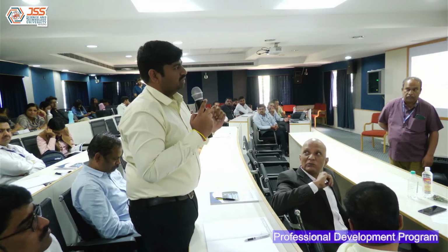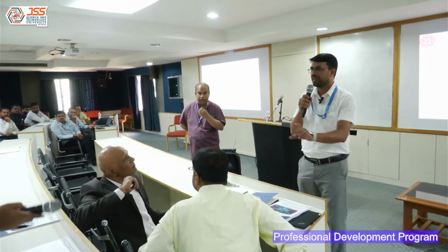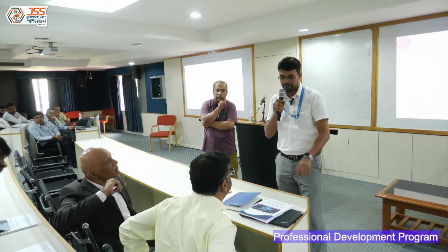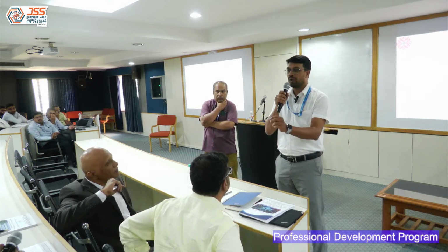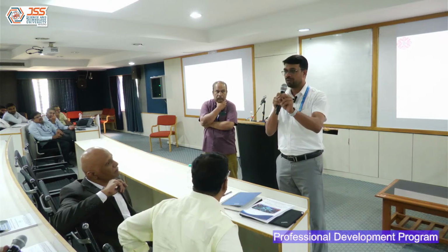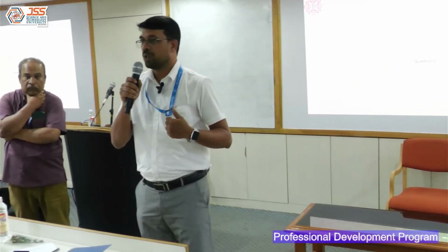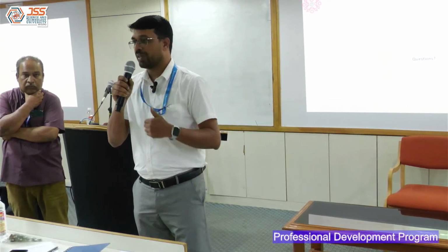Okay. I heard some of the last 10 minutes of what Vijay sir was talking about, and I think he was talking about a few corners, right? We were talking about various sign-off corners. When he says sign-off corner, it would be aimed at a particular temperature, voltage, and other physical parameters. For example, if my chip has to work at, say, Siachen Glacier, I know what's the lowest temperature it can go to there. So when I am designing and testing, I should make sure that I test for these conditions.